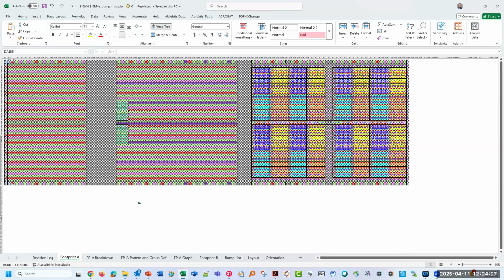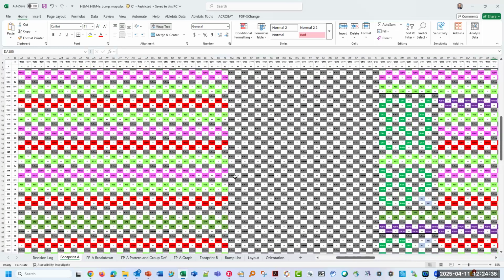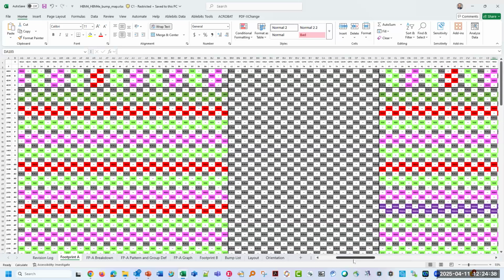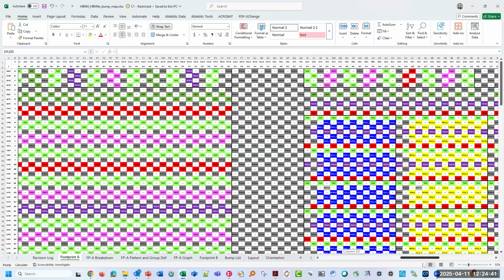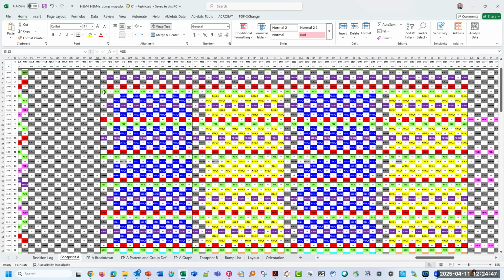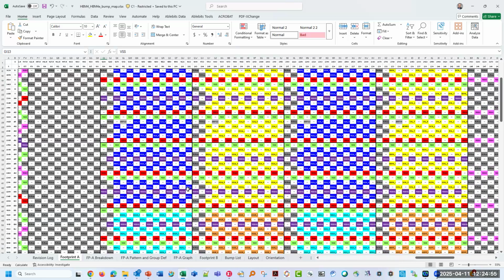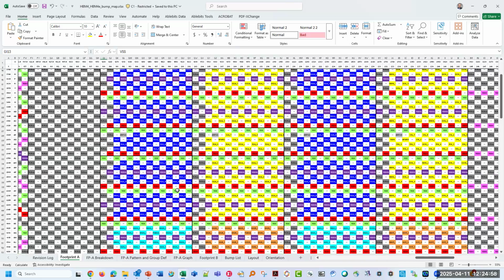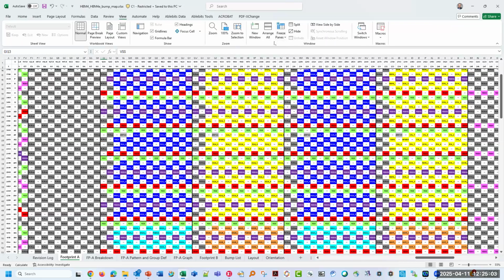If you zoom in a little bit to one of the channels, I can eyeball the bumps and tell you how different they are from HBM3. This is just the power and the direct access. The direct access is different, I can tell you that right now. So this is where you had the D word 0, A word 0. Okay, hang on. Yeah, this is the same as HBM3.